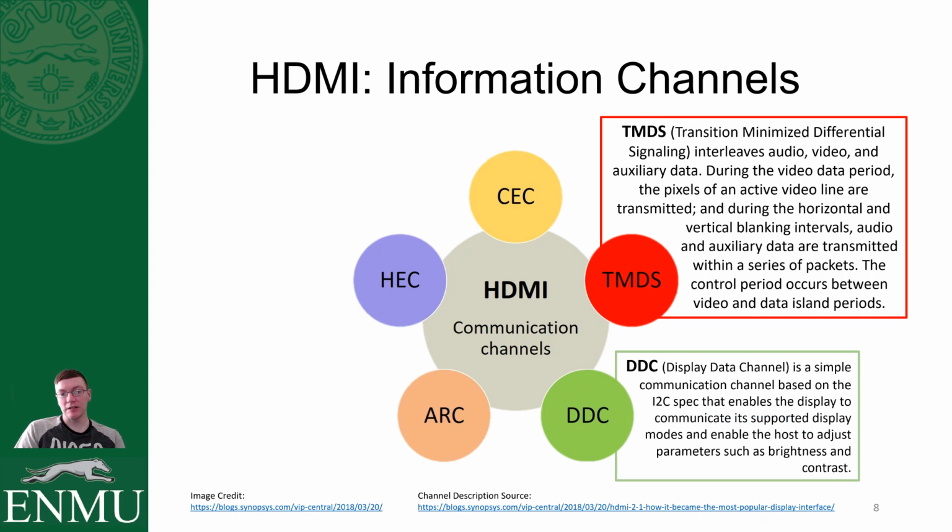DDC. So this is the display data channel. It is a simple communication channel based on I²C. And it's basically to allow for some awareness from the display and the source for compatibility. It's basically a table of hex codes that'll get exchanged over serial clock and serial data lines so that the devices are aware of each other's capabilities.